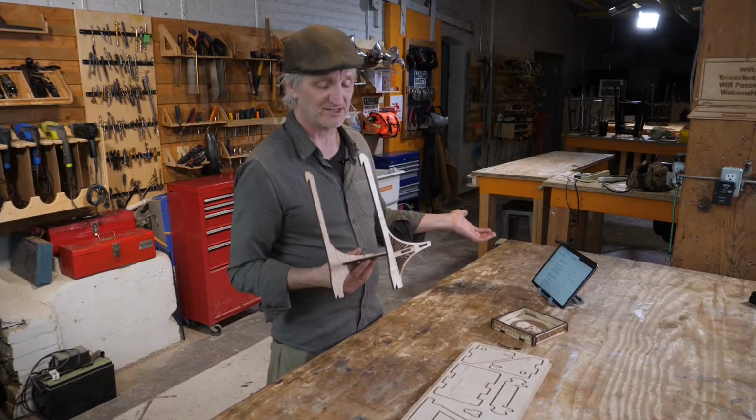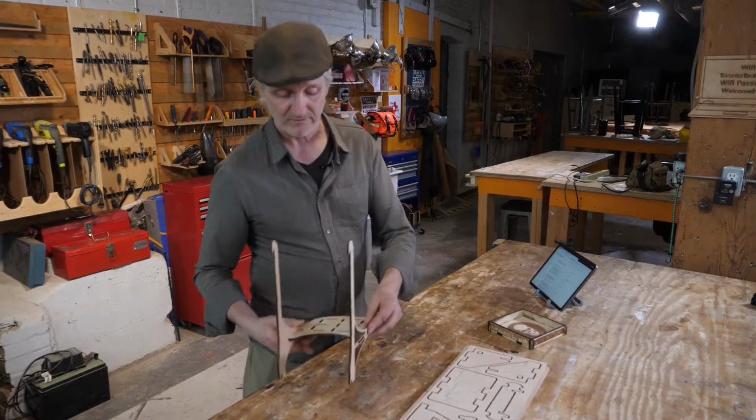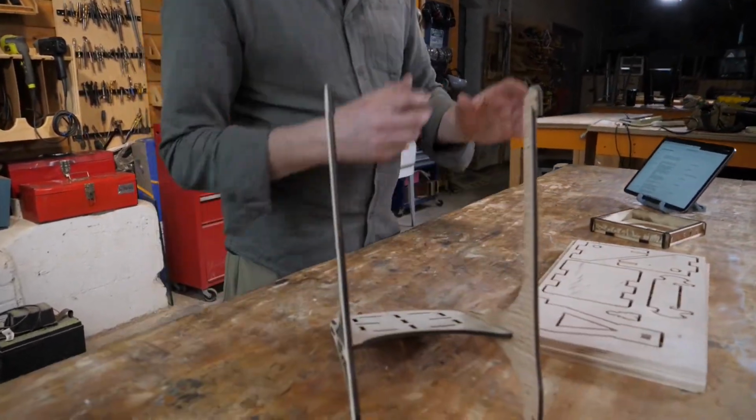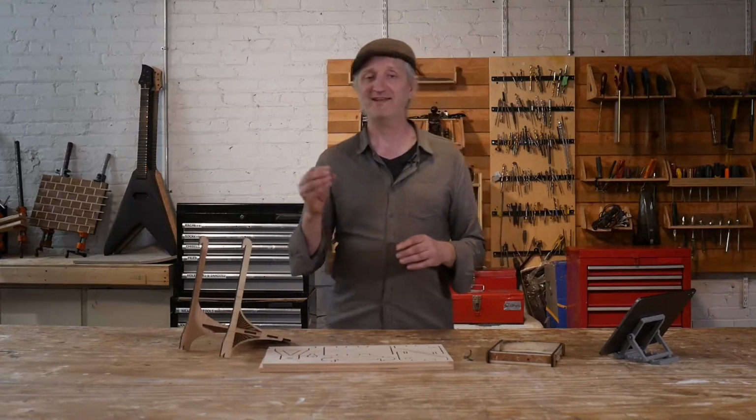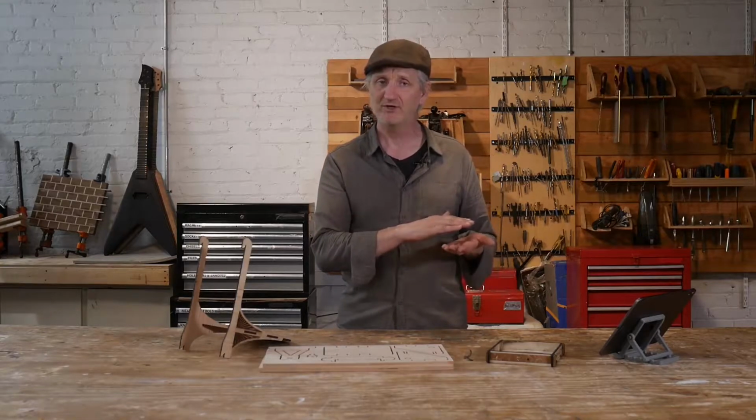Manufacturing standards can differ. So in this episode, to solve for this, we're going to be using a technique called parametric modeling combined with aliases. This is going to allow us to assign the thickness of our material inside the software in a way that if it should happen to change, the software can recompute the entire model for us, and it's going to be a huge time saver. So let's jump into the software and we're going to set up our project.